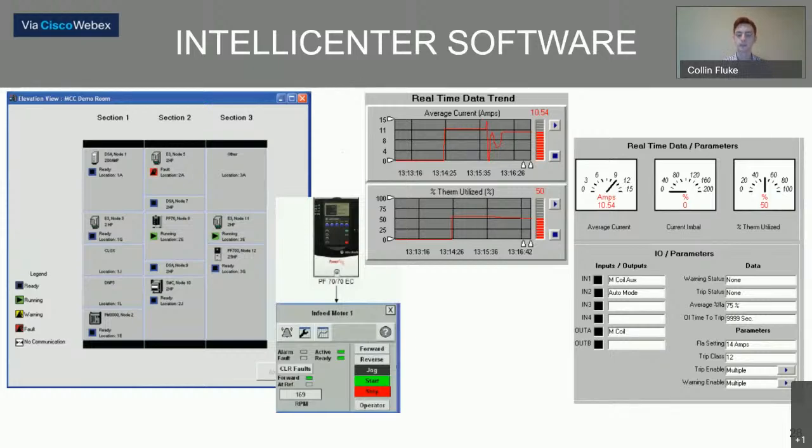So you're able to see, say, if an overload tripped at 3 a.m. in the morning, and you get in at 7:30 or 8 a.m. in the morning, we're able to go back and see, why was that overload tripping? What was happening before that overload? Or why were more amps being drawn? So you can always see the progressive patterns of what's happening in the MCC.